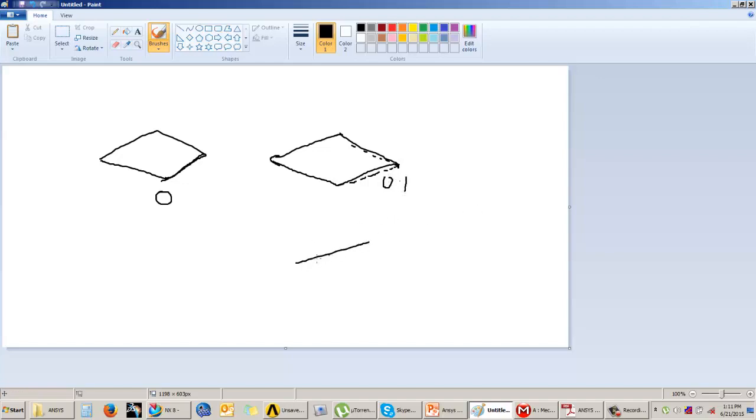Or let us say we have another element like this. So this is a perfect shape, but the element has distorted. Let us say the warping factor is 5. So this is nothing but the warping factor, where it shows us the out of plane deviation, how many planes are distorting outside.